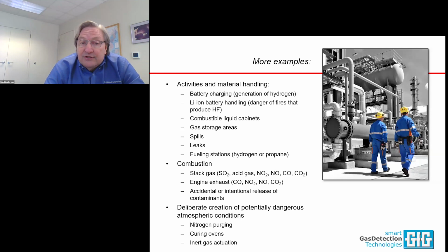Combustion processes. Stack gas includes SO2, other acid gases, NO2, NO, CO, CO2. Stack gas, if it drifts into the areas where workers are doing their jobs, can cause them harm. So make sure that you keep an eye on that, and if necessary, you do monitoring to ensure that you do not exceed the toxic exposure limits. And engine exhaust is always a concern on a construction site.